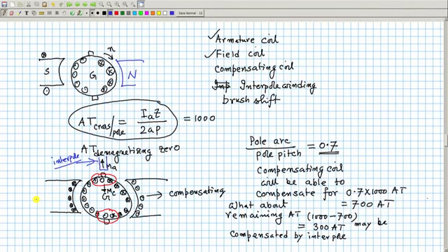And at rated current in a large machine, we know the flux per pole will effectively be slightly reduced and so on. Therefore, out of this total 80, how much of it can be compensated by the compensating coil? Maybe about 70%. To be very precise,